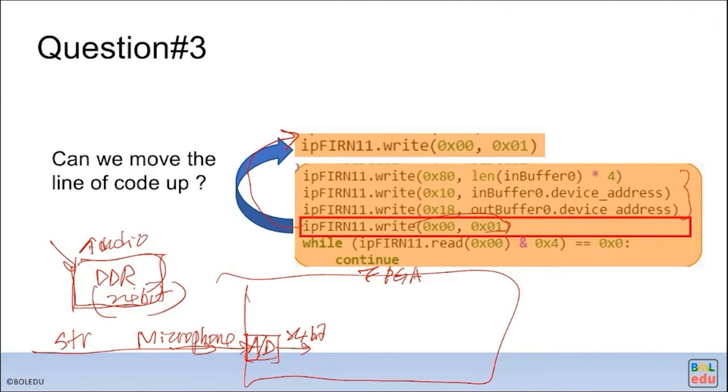The two are quite similar. For the one in memory, you may use the DMA engine from MM to S, from memory to stream. The memory is 32 bits, and the bus interface right now is 64 bits, high performance transport.